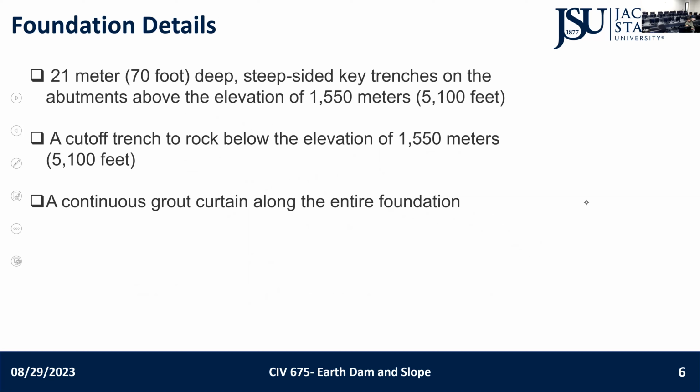Besides, there was a cut-off trench of rock below the elevation of 1,550 meters, and below the foundation there was a continuous grout curtain to block the seepage of water below the foundation.